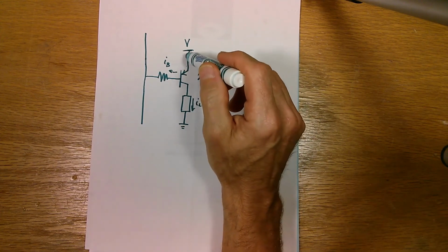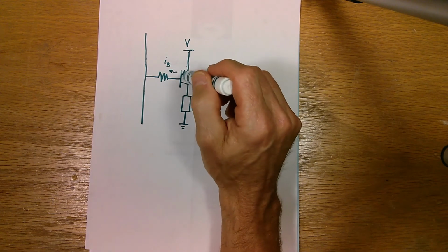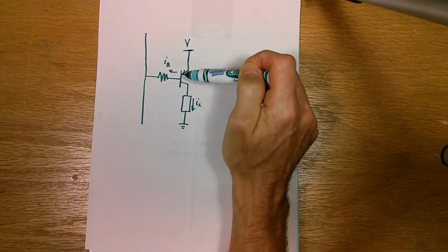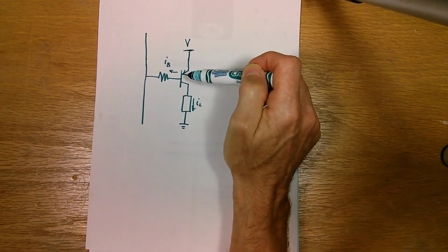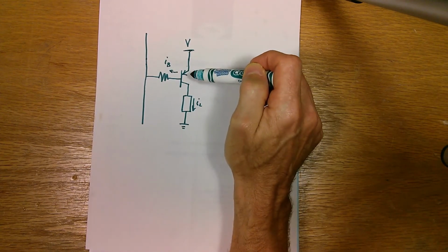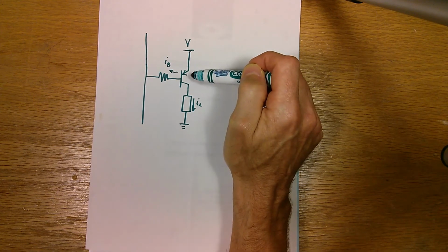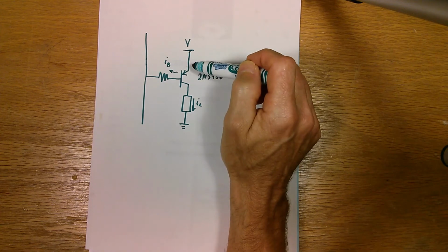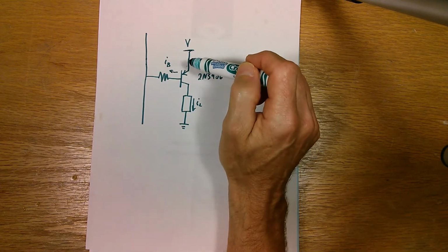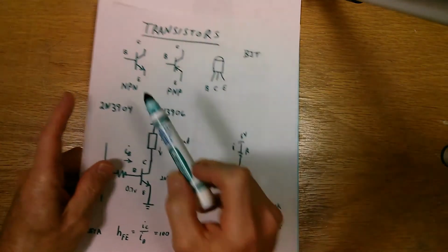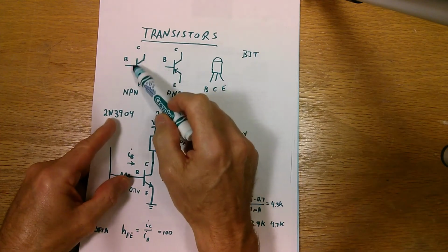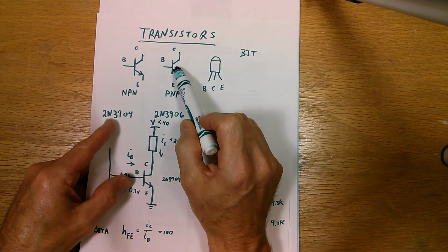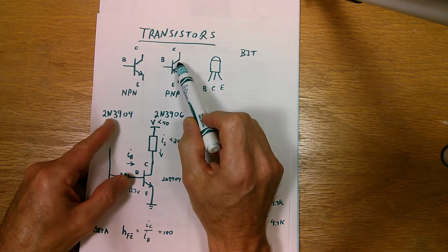The reason for that is the manufacturing process is different between a PNP and an NPN, and the transistor is not as efficient. I can go into the details of the construction of a transistor and the mobility of the charge carriers, and what they call the majority carriers. In an NPN device, the majority carriers are electrons, and the majority carriers in a PNP device are called holes, or lack of electrons.